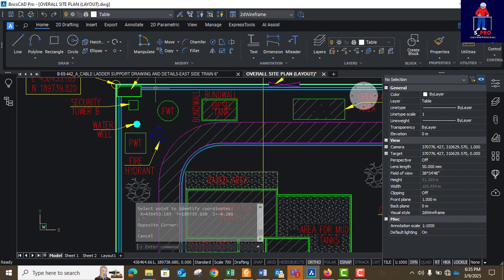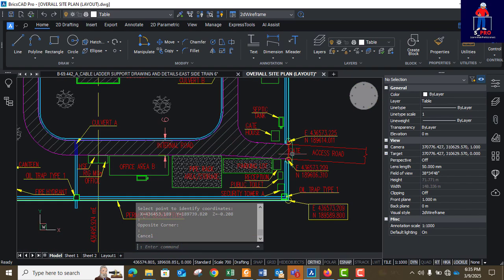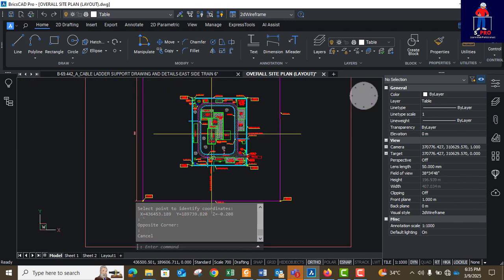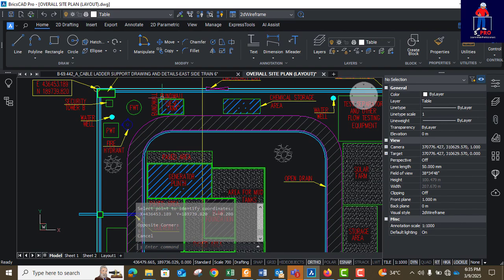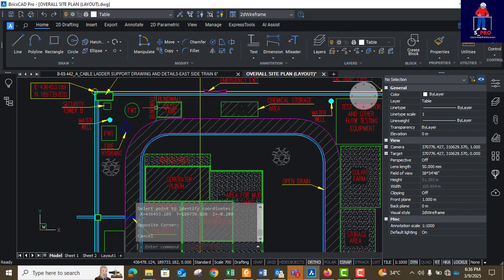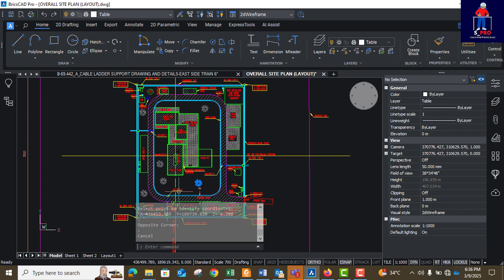Then after that we see the access road and internal road. Actually, how you route your internal road is based on what you have inside the facility. Like if you look at this one, you have a pond wall and the diesel tank. Of course, from time to time vehicles will be bringing in diesel to this place, so we need roads that the vehicles can ply to get to it. Easy access to the equipment is very important for maintenance purposes.